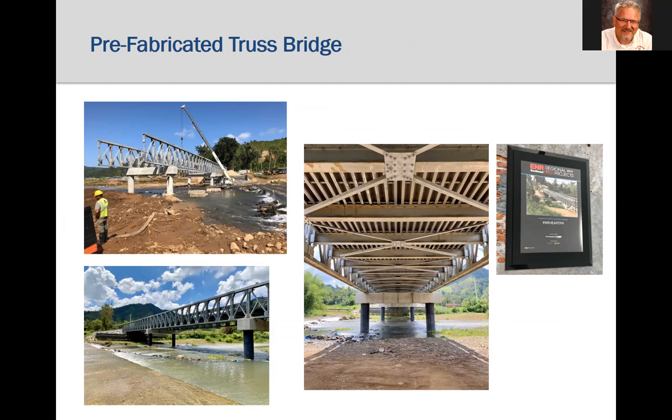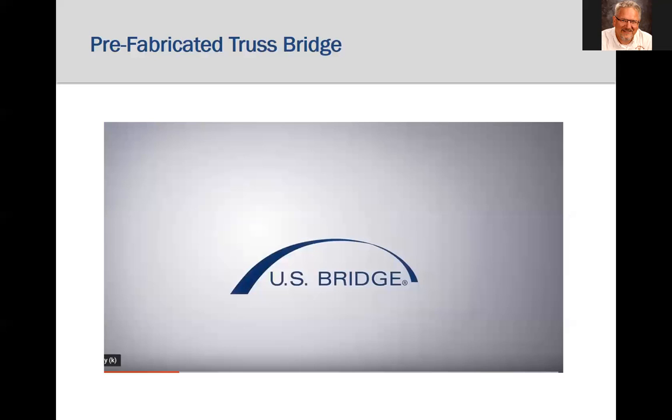This particular bridge, out of the 5 sent, was a 24-foot wide, 3-span continuous truss with spans of 106 feet, 98 feet, and 160 feet, weighing 318 tons and shipped in 17 containers. The steel was galvanized for longevity and low maintenance. The bridge won the Engineering News Record Southeast Best Project Award in 2018. This is a short video, but it shows the erection of a 3-span prefabricated truss bridge.